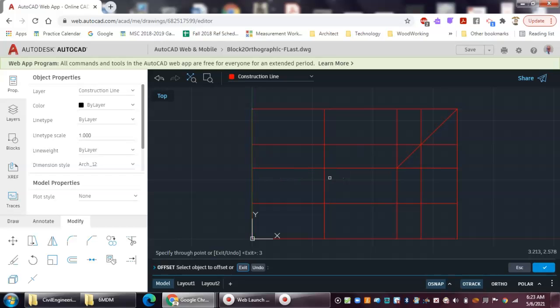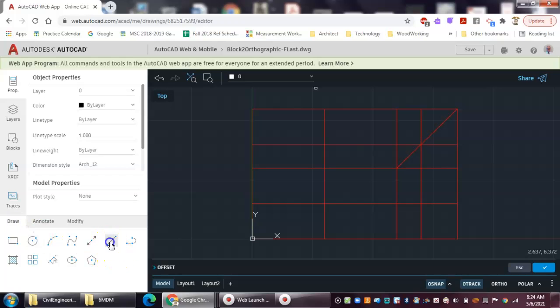All right, so now I've got all my construction lines to draw what the object or the real line should look like. So let me go back here and make my object line view active so I can draw on it. And at this point, it's just a matter of going back and drawing these lines for each of the views. So I know now that I've got all these points, I really know where my lines fall in. And again, notice how that almost picked up on the midpoint of that construction line.